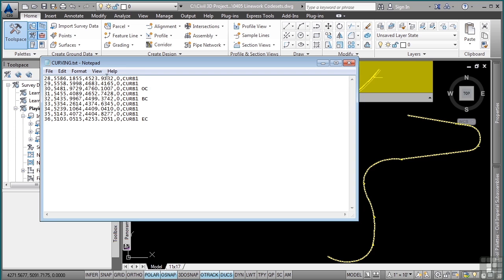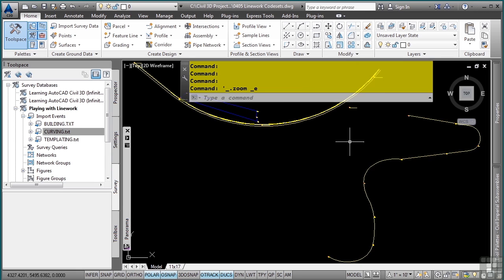So what you'll notice here is I do not have any, and I mean absolutely anywhere where it's defined as PC, BC, EC, etc. before this curve. I do, however, have it afterwards, okay? And here's some other functionality going on, is that I simply have a begin curve and an end curve, and it automatically will calculate out the rest of the curve information in between. In the past, you used to have to code this as multi-curve points, but now you no longer need to do that. So I'm just going to close this file, and let's go ahead and view what's going on.